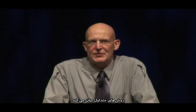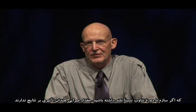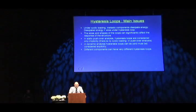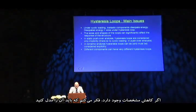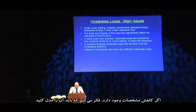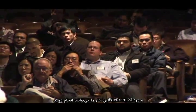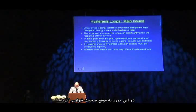The conventional wisdom says if you get into rather long period structures, the amount of damping shouldn't have very much effect on the result. But that doesn't always seem to be the case. This is a little tricky one. If there is degradation, then I think you should attempt to model it. And within Perform 3D, you can do that. We'll talk about that in a moment.